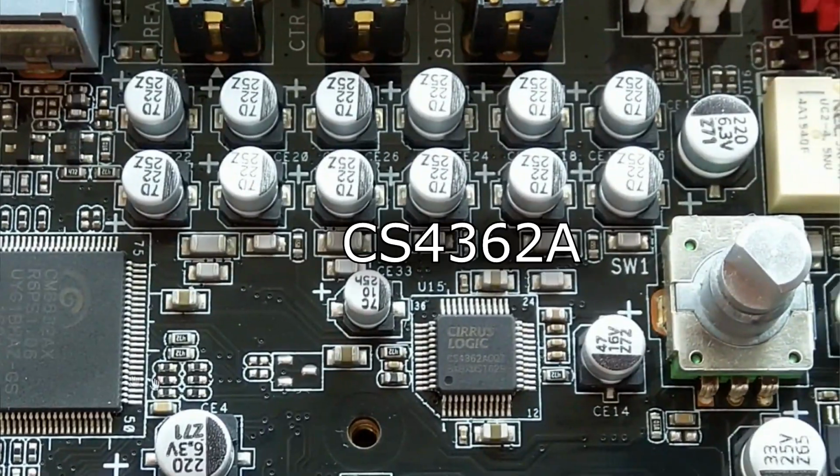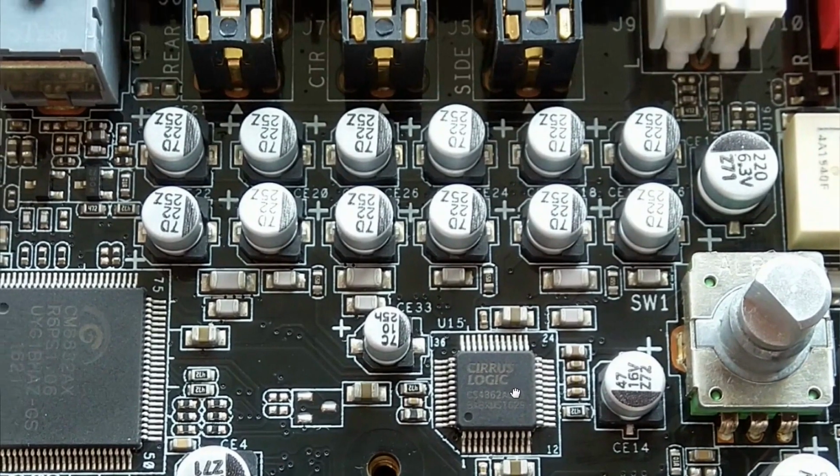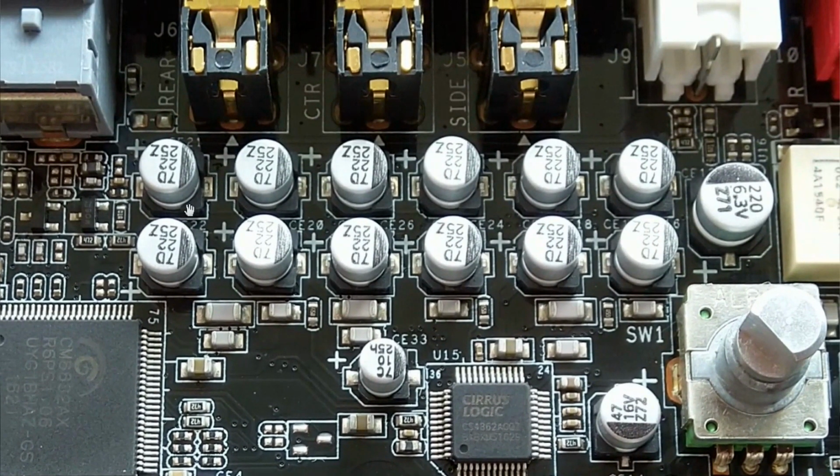And moving over, what we have here is a multi-channel 6-channel DA converter, and that is for the surround outputs. And over here is all the coupling capacitors, because everything is powered by 5 volts. So to get rid of the 2.5 volt DC, they use coupling capacitors here, and you can see we've got the outputs here: rear output, center, side, and I think it's got the subwoofer here as well.